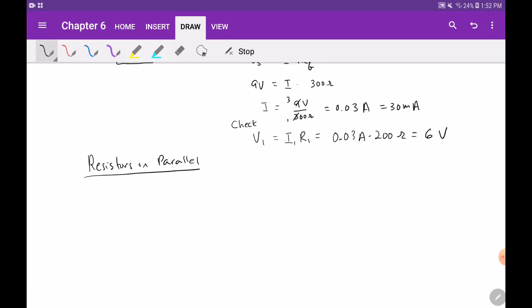Okay? I want to point out one thing, that this is really useful. Just studying a circuit with the resistors is very useful in our studies when we have capacitors and inductors later, because we're going to take Laplace transform of the whole circuit, and everything will become impedance, which can be treated as if they're resistors. So let's see the resistors in parallel.